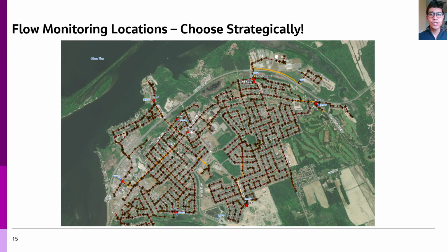So for each flow monitoring location in here, we develop RTK for short-term response, medium-term response, and long-term response. For each of these flow monitoring locations, again, I know I'm repeating myself, we're going to calibrate 9 RTK parameters.